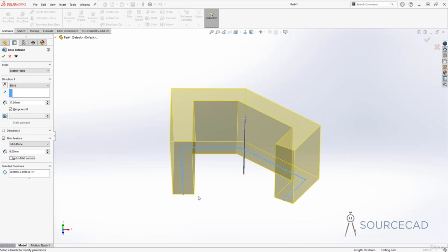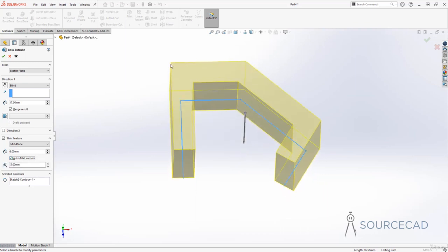sketch. Now we have a checkbox called auto fillet corners. When you check this box, this will add fillets on all of these vertices. Right now the preview is not visible even though it is added. Let me show you how to see those things, those changes. But first, as you can see, the thickness is 6 and the fillet is 5, which is kind of big. So I'll just make it smaller. So I'll make it 2.